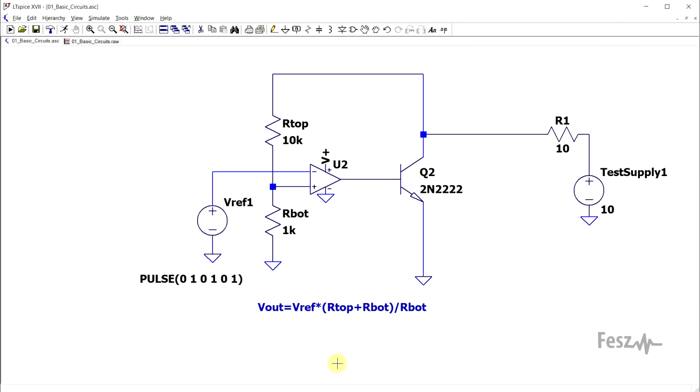Anyway, moving on to the constant voltage source, I used a similar set of components, but there was one important change. I had to use a resistor in series with a supply just to see the voltage to which the active load ends up stabilizing to.